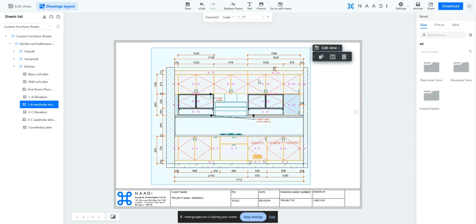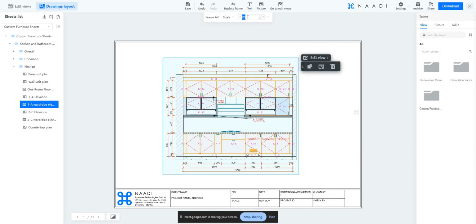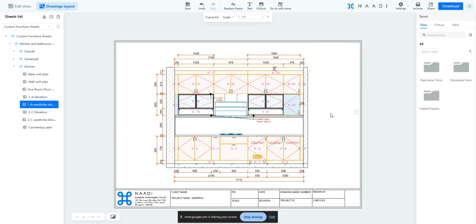And right now, if I just select this drawing, on the top, can you see it is showing the scale of the drawing, right? I can define it. There are some standard scales here, or I could also go for any custom scaling as well. So these are all the things which you can do. Okay, so that way, can you see for each and every drawing, you can just configure the scale, configure the dimension alignment there in the edit view so that everything will be proper, and you can place it in your sheet template and take it further.